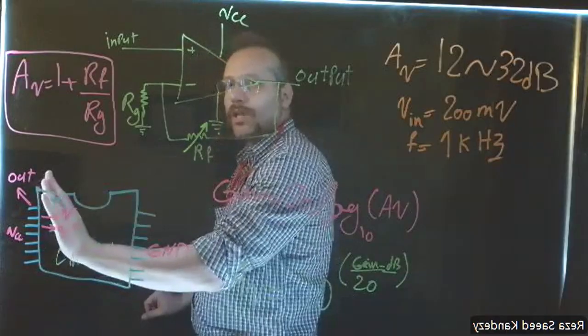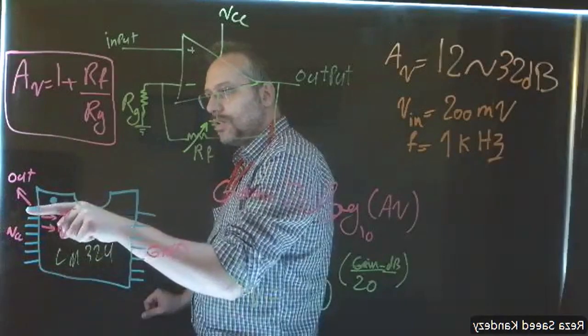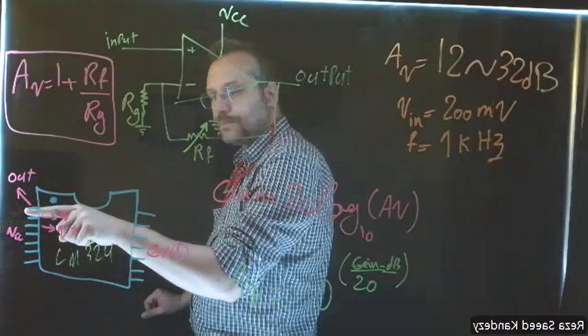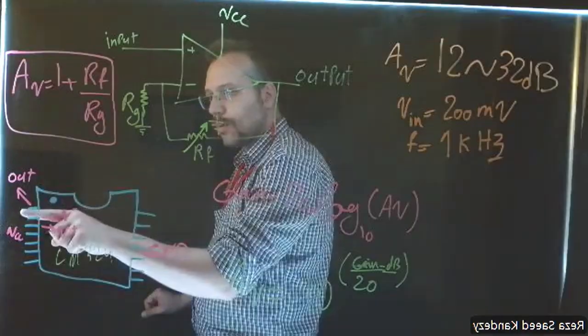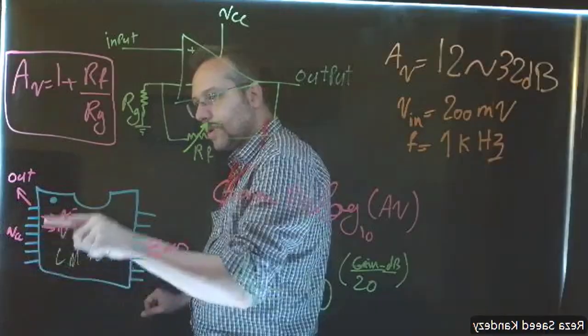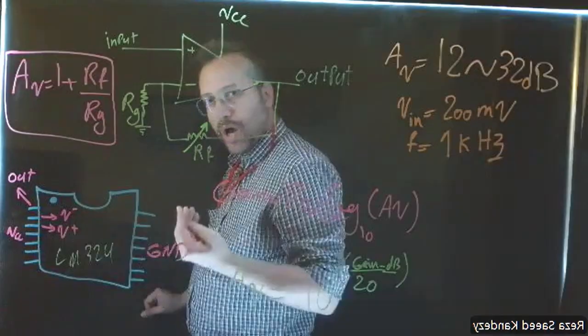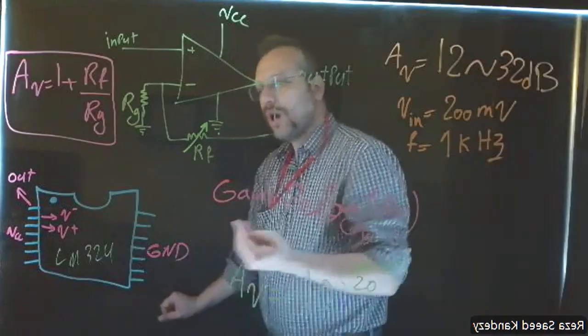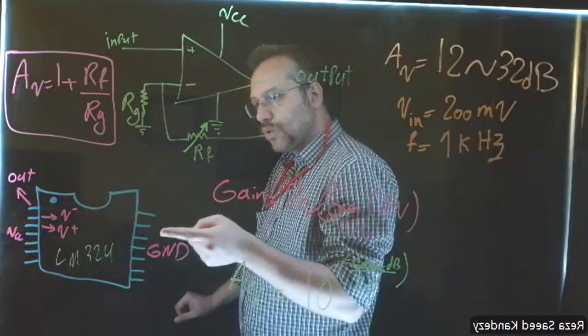The left side will start with pin number 1 in the top. So the left top pin is number 1, and then you can number them from top to bottom: 1, 2, 3, 4, 5, 6, 7. And the right side is numbered from the bottom to top: 8, 9, 10, 11, 12, 13, 14.